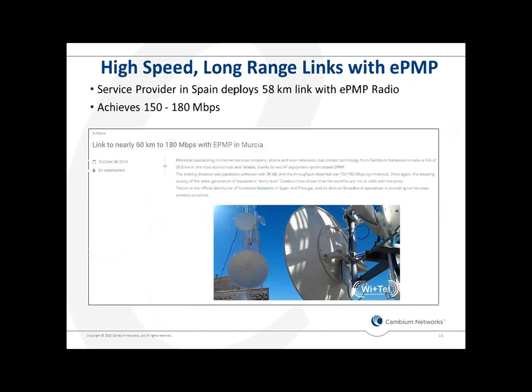We have a lot of people out there using the ePMP in point-to-point mode. Here's a very interesting case. Recently we had a service provider in Spain who deployed what I think might be the longest ePMP link out there. They used a very large dish. This is not a force dish. This is probably a 3-foot dish here. It's a 34 dBi dish, and they were able to achieve 58 kilometers with their ePMP radio and 150 to 180 megabits per second of throughput.